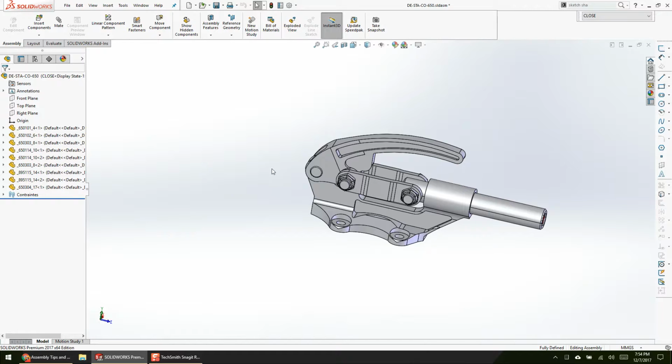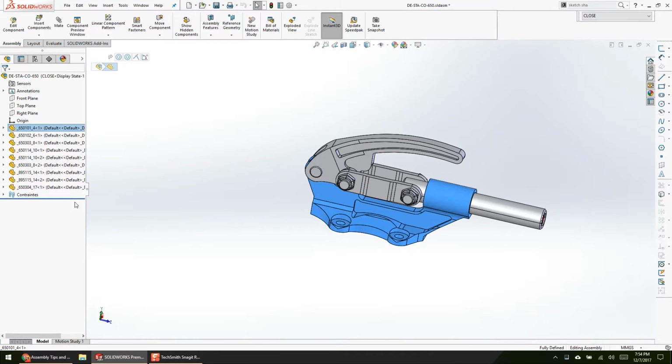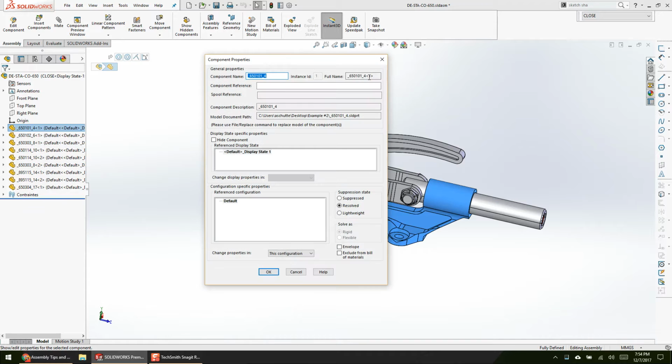So, new thing, I think SolidWorks 2015 or something, they came out with this. What you're able to do is click on any part in any assembly. So it's any component in any assembly. You can right click on it and say make virtual. What make virtual will do is turn the assembly into basically a giant zip file. It'll take all of the parts and embed them in the assembly. You can delete the part files off your hard drive. And I'll demonstrate that accordingly.